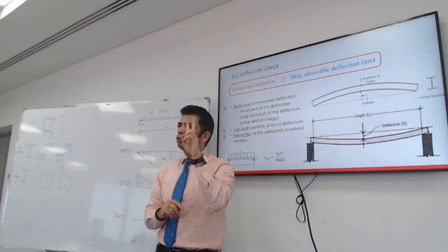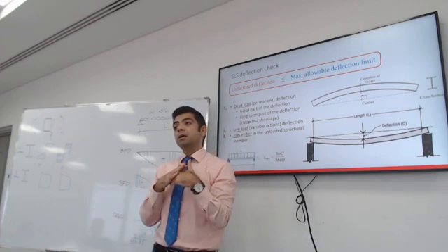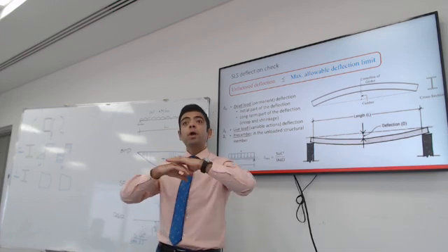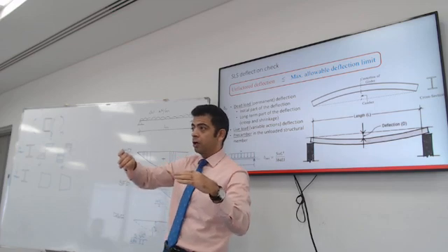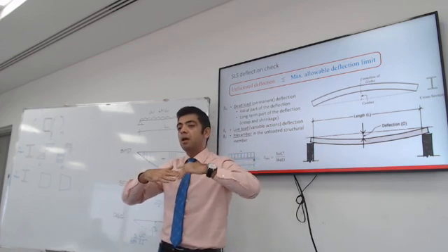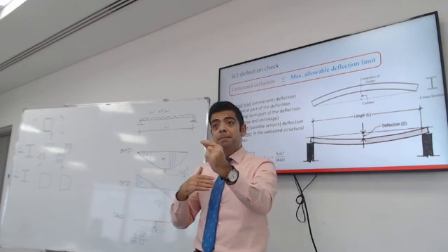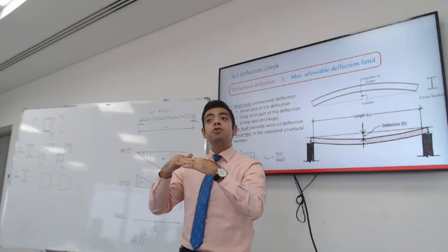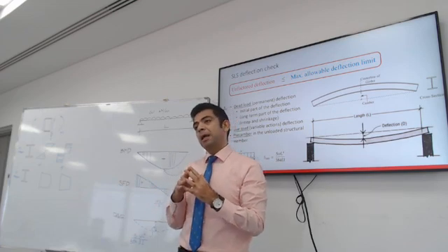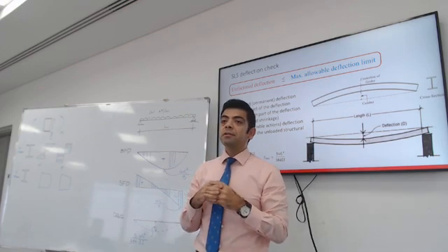There are two kinds of dead load. There is the short term and long term. Short term, when you finish pouring the concrete, immediately that weight is dead load. There are factors that depend on time, like creep and shrinkage. These are factors you probably heard about in your study of concrete material or structural materials.